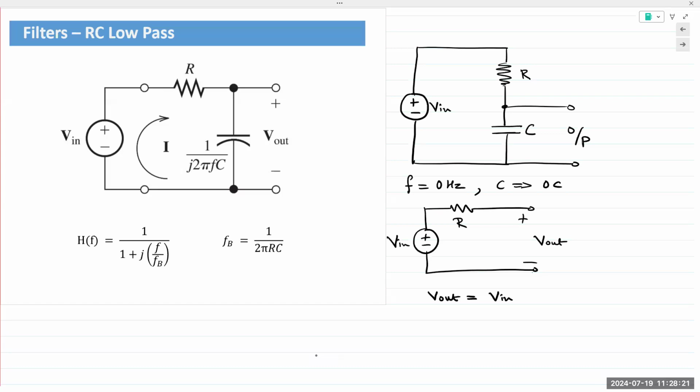In terms of circuit analysis, you could think of it this way. V in is applied to the capacitor through a resistor R. When it first begins charging, current is flowing through the resistor, electrons are flowing through the circuit, and the capacitor is building up charge. Once the voltage across the capacitor reaches a level of V in, both ends of the circuit are at the same level, there is no more charge imbalance.